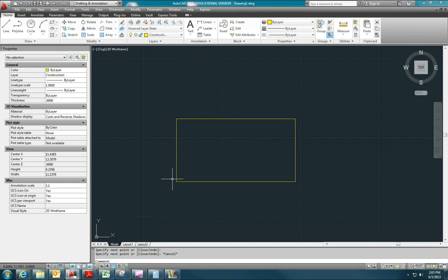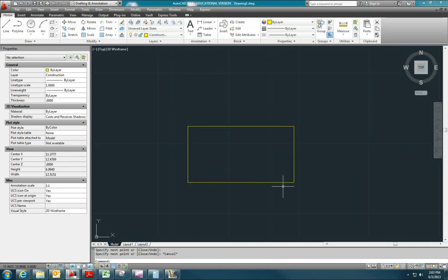Okay, now if you're confused about the front, top, and right side view, remember we're dealing with a box here, and anytime an object is given in an isometric view to us to reproduce, the front view is as if you were standing at the lower left corner of the object and looking back toward it. It's a little hard to describe verbally, but I think you'll see which view I'm drawing, and that's always the arrangement of views if you're given an isometric view. And I will demonstrate that as we move along. Okay, so this is the outline of the object,